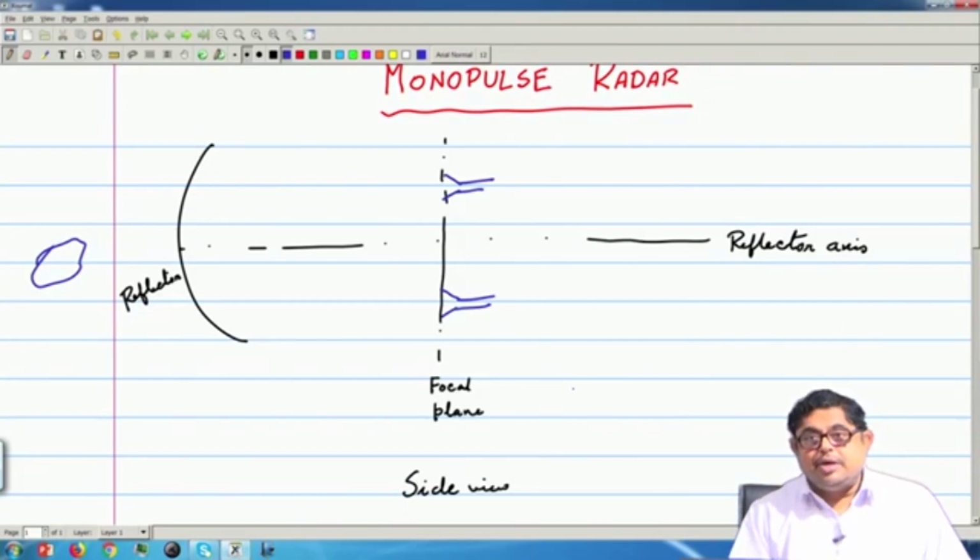So, from that it could have been ascertained, but people found that this way a lot of error comes in the measurement. Why? Because every RF receiver has a local oscillator. So, though all the references may be synchronized, with time there is drift and that drift produces a lot of error. So, the actual measurement was erroneous and angle measurement was not so precise.